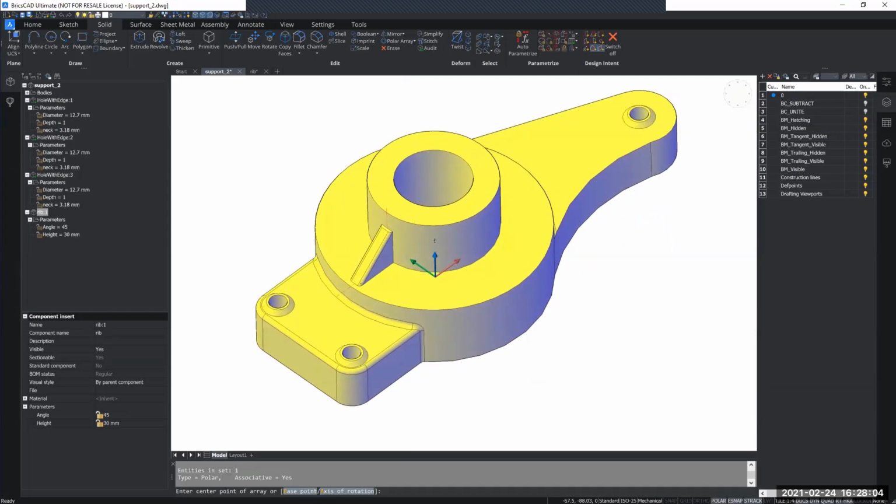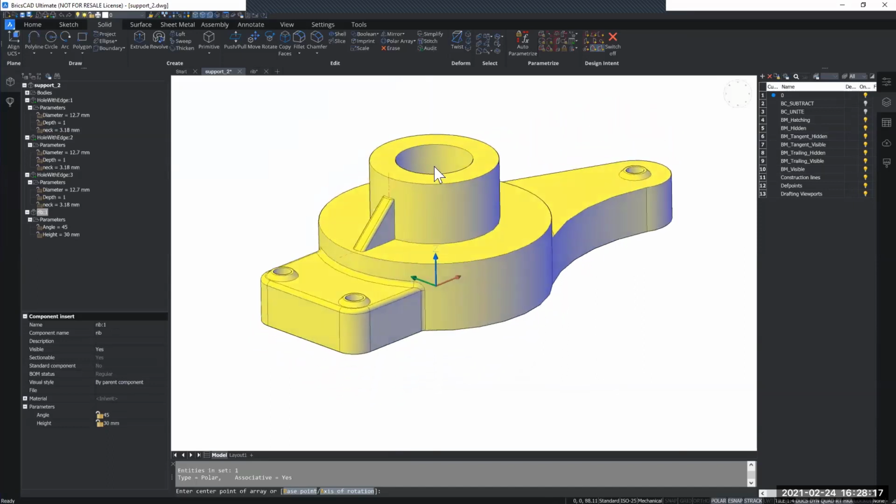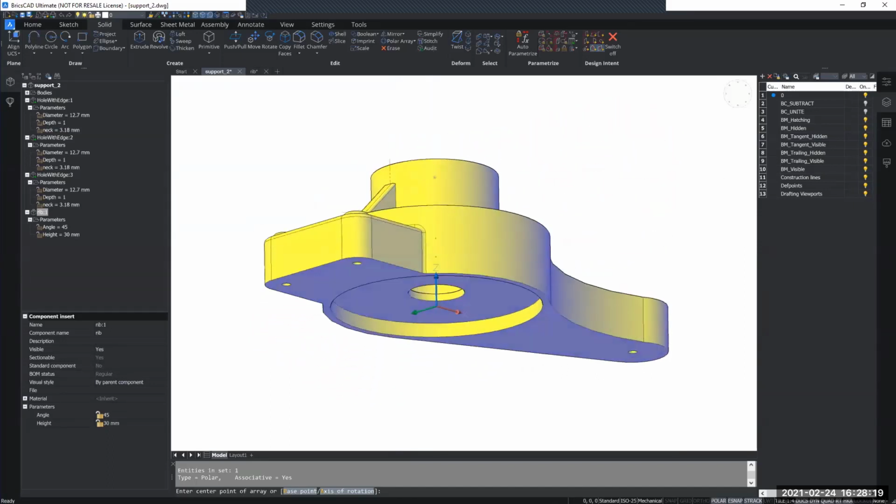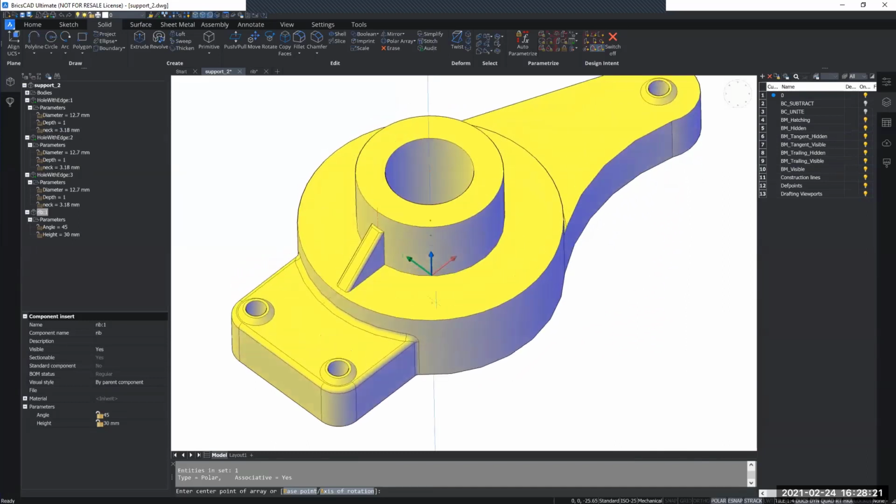If you have not defined any kind of circular location yet, you can then again use the axis of rotation sub option, and you can draw a line that goes through the middle from the top to the bottom here, for example, and it will define a center line it will revolve around. But I will just select the center here.